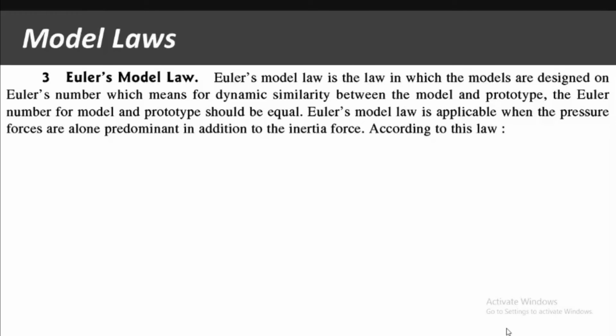So now we are going to see our next model law, that is Euler's model law. This model law is mostly applicable between the prototype and model for dynamic similarity, in flows where the Euler's number plays a very important role.